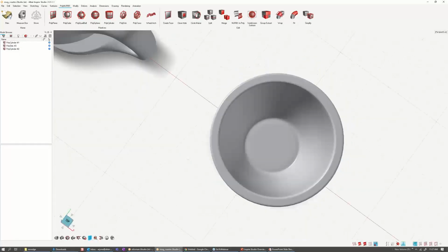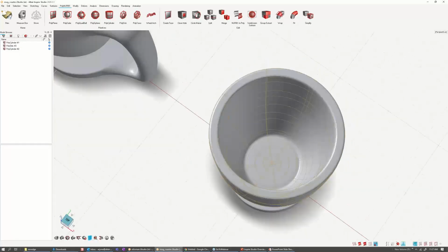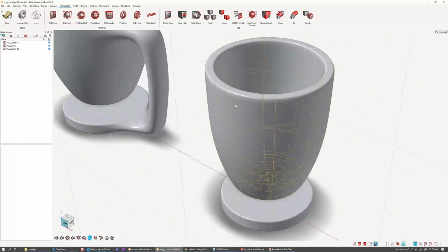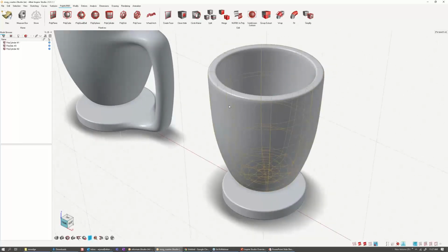If you want, you can add a strength on the inside too, and you can get the same effect by adding another loop at the very top. But adding loops to the top makes the model more complex, so you can rather use the edge creasing instead of adding another edge or even adding a chamfer. But let me show you what I mean by that.